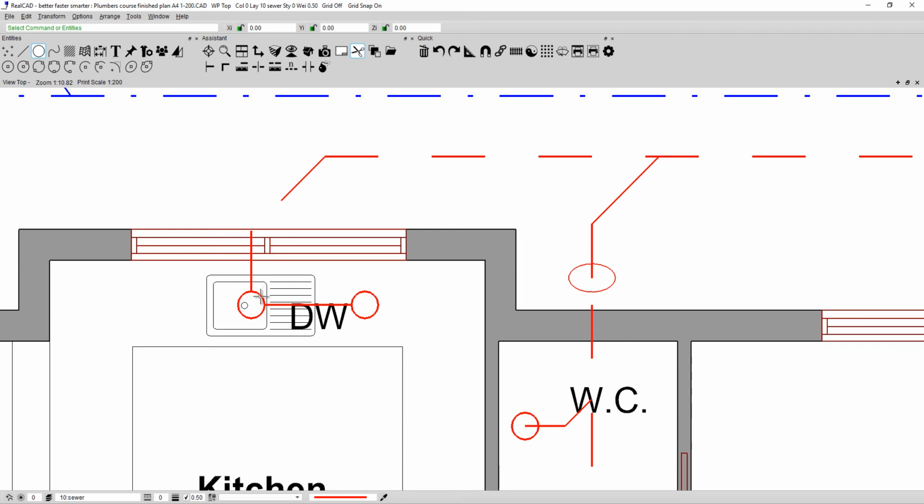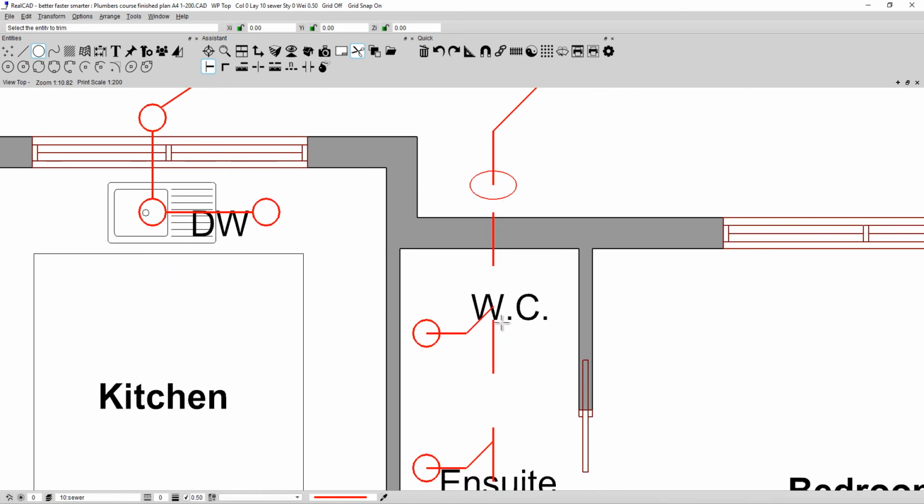I know that this was in line, so I'm going to pull that out, make the copy there, and I'm going to bring this line and join this line up with, say, the middle. Notice my cursor is a little point. See a little point, little circle? That means I found the center of the circle. Okay, I want it to be snapped to that center. Now, why isn't it snapping? Can anyone tell me? Yes, it's because we have the grid switched on. But I'm also quite happy that that's in that location, so I'm very happy just to trim that back to there. I think that looks neat enough, and it's certainly exactly as it should be, really, for what we're after.